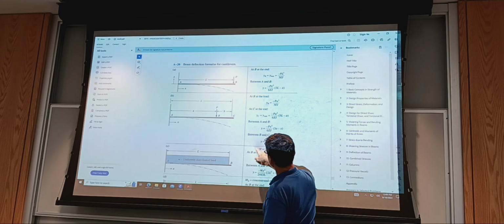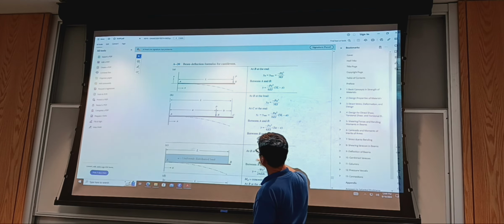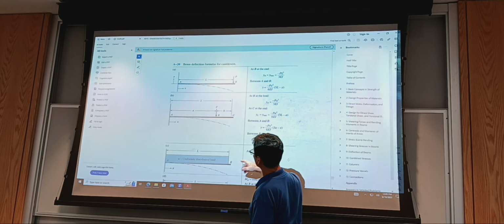Notice it's something that we discussed in class. So capital W is the total load, essentially the area of this uniformly distributed load. Okay, so there's this note here, and I use it elsewhere too. Capital W is lowercase w, the uniformly distributed load, times the length over which it applies. And I've seen students using lowercase w in the formula for YB. Both are negative, because the y-axis is positive up, and so yeah, that was it.